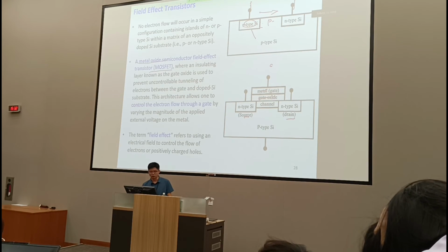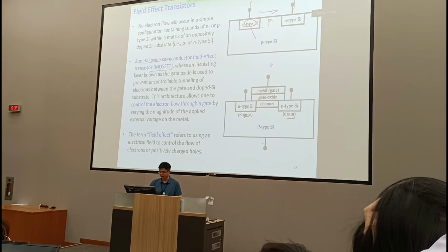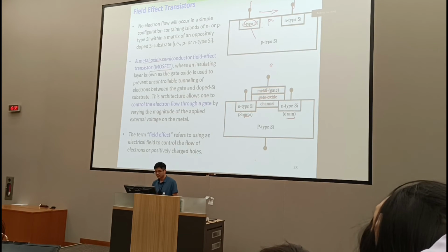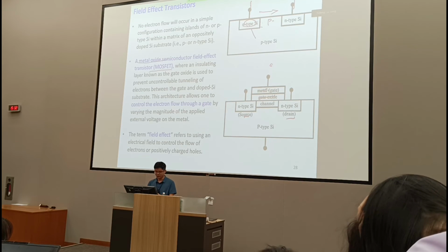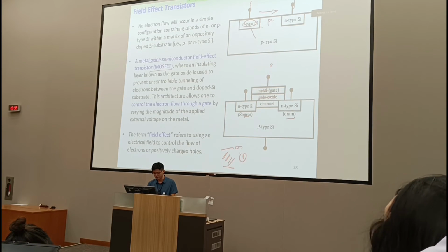At the bottom you have the gate oxide. The channel is p-type silicon. So you apply this voltage between the gate and your p-type silicon. You can think of the p-type silicon as a conductor, with an insulating layer between. You have two metal plates, and you have the voltage across, right?